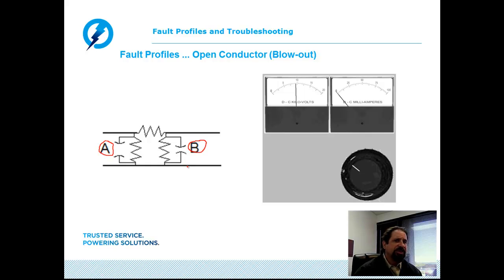The reason for this is, if you remember, when a cable fault fails, all of the fault current travels back toward the source along the path of the neutral or shield. Now, when a fault flashes over, the intensity of fault current, depending upon the magnitude of the fault and the voltage values at which it flashed over, can be several hundreds or thousands of amps.